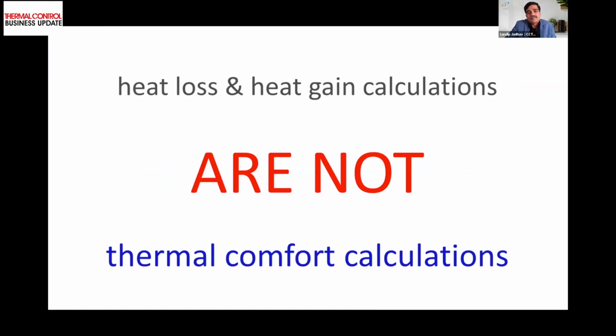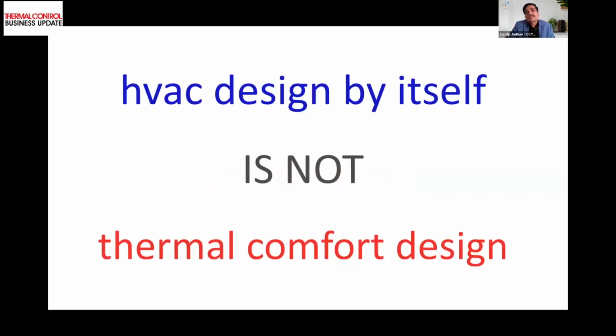Another thing is many people misunderstand and say, oh, I've done a heat load calculation, I have done the heat gain and heat loss, so I got the thermal comfort. Please, that's not thermal comfort. That's what you do for sizing your HVAC system. That's what you start with, but that's not the end. And again, people say, okay, I put up the best system, I got an HVAC design, I put up the diffusers, I'm done, and now you should feel comfortable. It's as if that person is responsible for feeling comfortable. It is not that. HVAC design itself is not a thermal comfort design. Thermal comfort design actually starts after this. If we understand this, I think we are in the right frame to understand more about this subject.